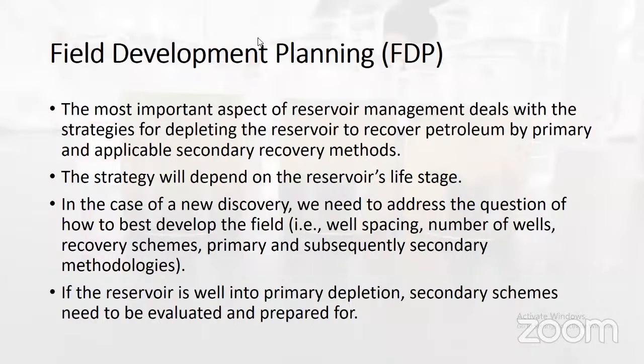So if we try to produce from this field at the maximum production capacity, the reservoir pressure will go down very fast below the bubble point. That will cause some gas production problems that will, in the end, reduce the oil production rate. But what if we have a reservoir that is very far from the bubble point?